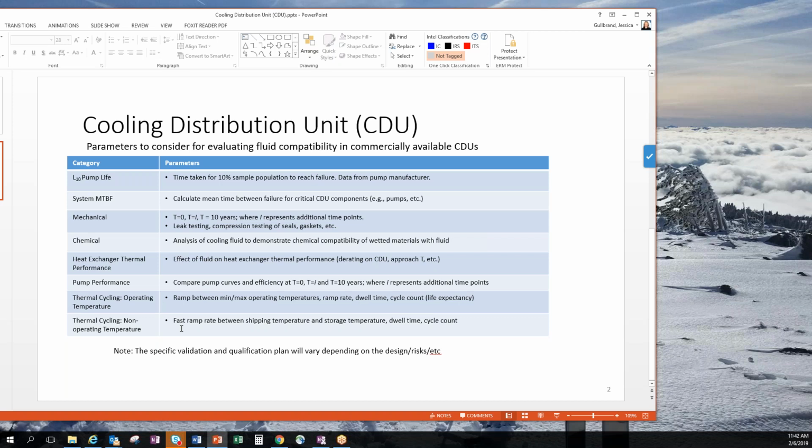The life of the CDU, if it's related to the life of the pump, and it probably generally is, is going to depend on how good you are at filtering stuff and how carefully you picked out your coolant additive to be compatible with the seal materials. And of course, it depends on what water you fill it up with. If it's hard water, if it's got any abrasive stuff in it at all, then it's not going to last.